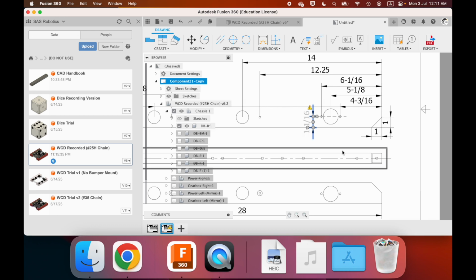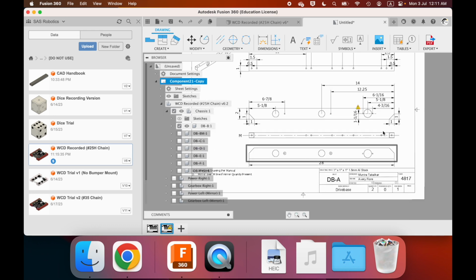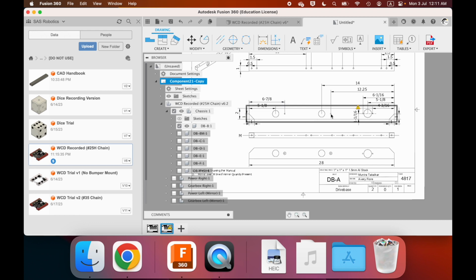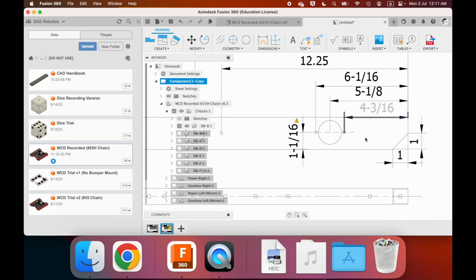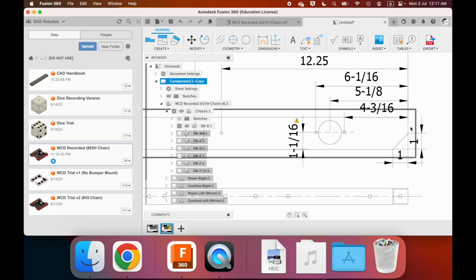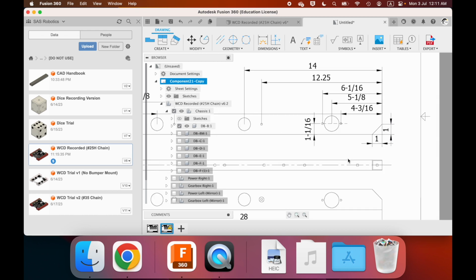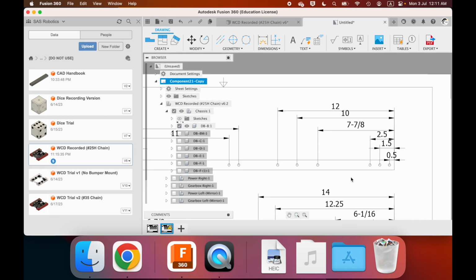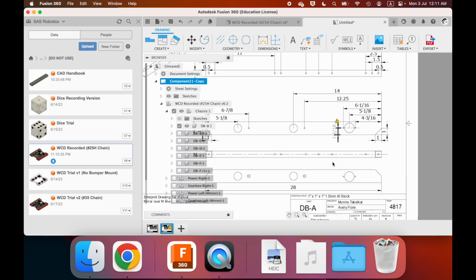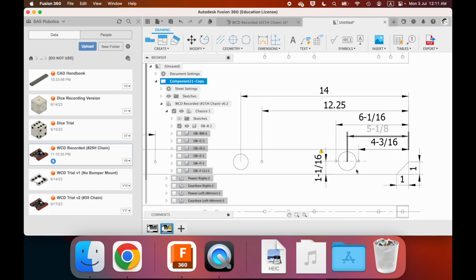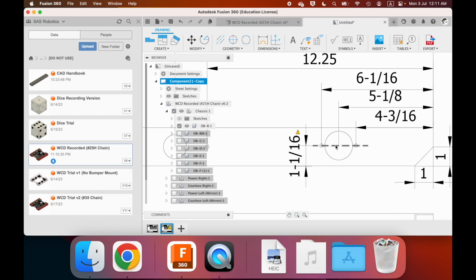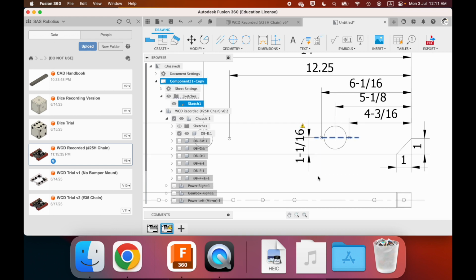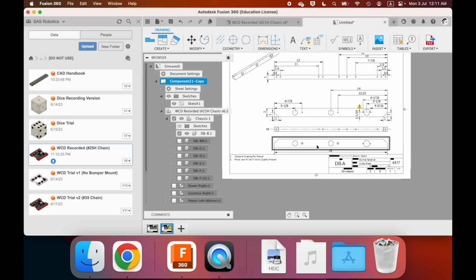Often these dotted lines would go through the entire thing, when you have multiple holes spread out through the entire stock on that line. Okay, and that means you might have to do that line trick I showed you. You draw a line here, you draw a line, and then if this piece is stock, you extend, you delete the additional lines you drew, and then you can dimension it properly like this. Okay, this case, it's a special case, and that's what I think makes sense there.